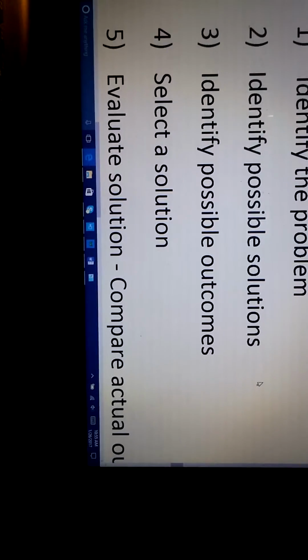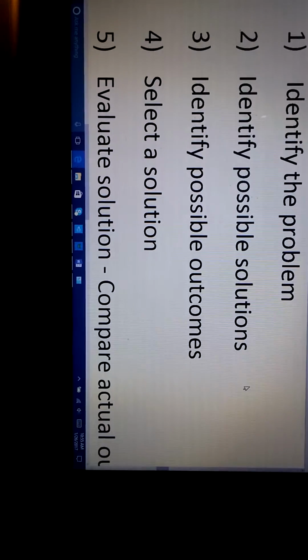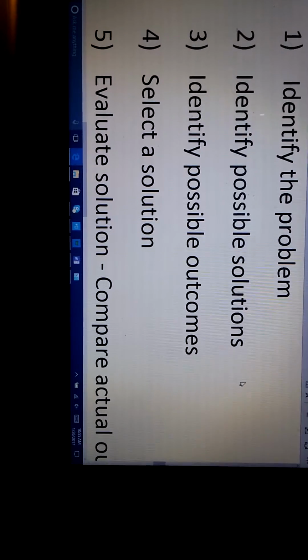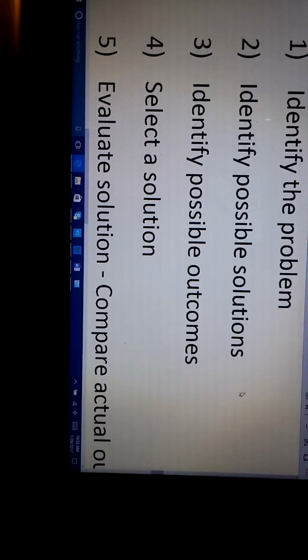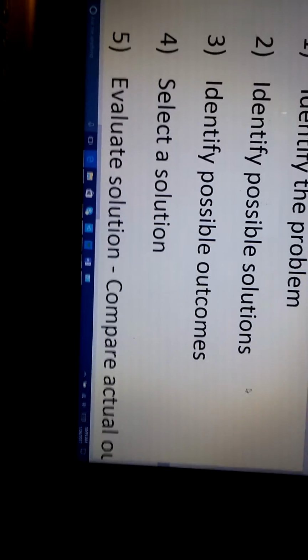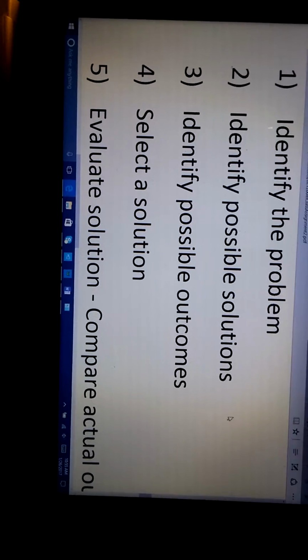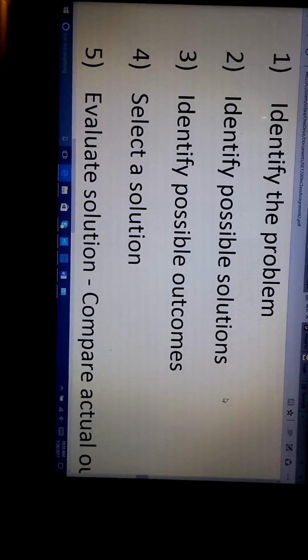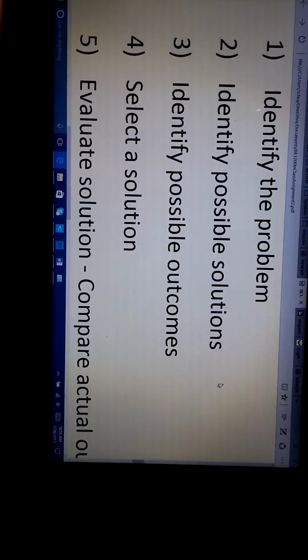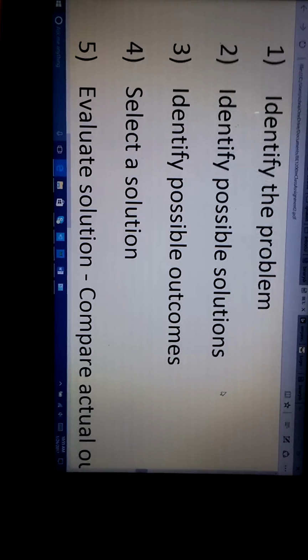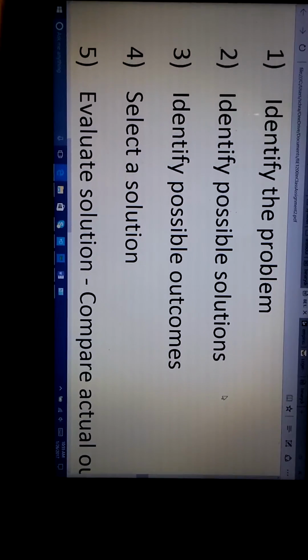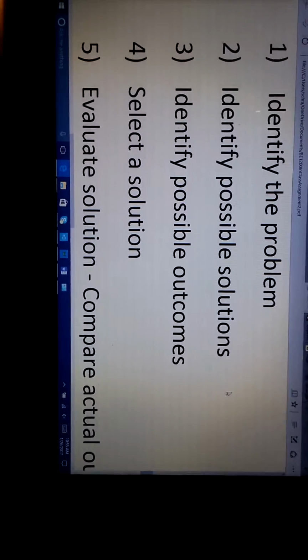So my possible outcome may be really not a negative effect, or the negative effect could be that off-peak hours I'm stuck with the pre-timed signal that's causing excessive delay and excessive waste because I can't go into a smart detection mode because the detector's out.